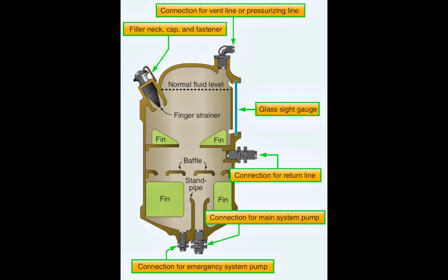What is the function of a wing flap overload valve? Prevent damage to the flaps if lowered at excessive speeds. When installing a chevron seal, what must be considered? Pressure toward the open side of the seal. When hydraulic lines have been disconnected, what precautions should be taken to prevent contamination of the system? Capped or plugged immediately.